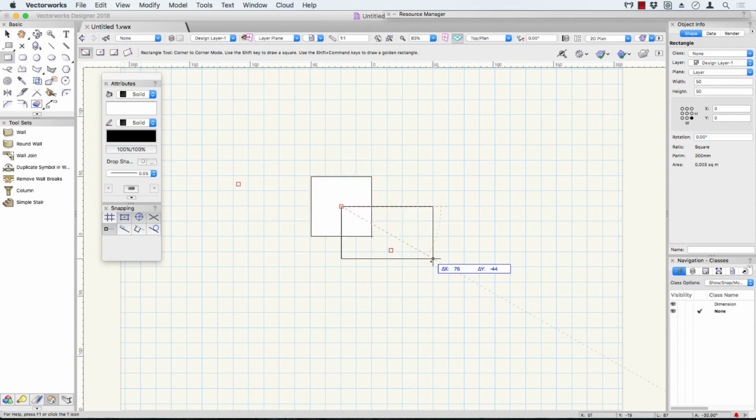Click to start a rectangle and go to the center of the first rectangle to click, and you'll see that we can now create a rectangle. And there's this blue bar, which is the floating data bar, and I can now type in 50 or 2 inches, 50 millimeters, hit the Tab key, minus 2 inches or minus 50 millimeters, enter once just to see what it looks like, and enter again to confirm. Now you can click with your mouse if you like after that first enter, but I find it much quicker just to hit enter twice.